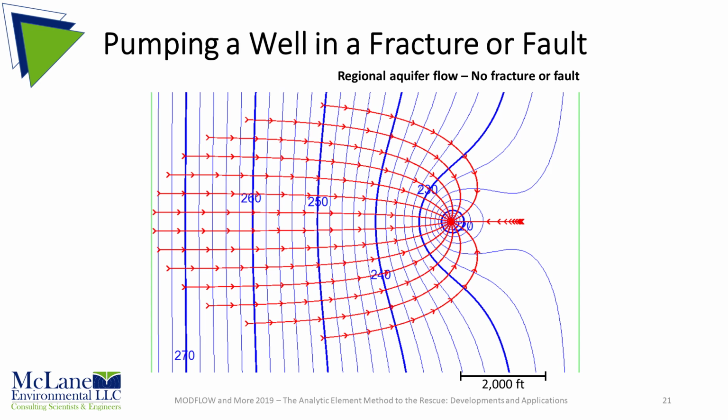In this model, we are going to examine the hydraulics of a well pumping from directly within a fracture zone. It is well known that if a well is located to pump water from a transmissive fault zone, the well can produce greater yield with less drawdown than a well located somewhere in the body of the fractured bedrock aquifer. We can build a simple AEM model to demonstrate that.